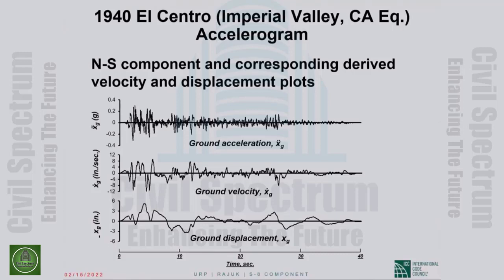I think I mentioned previously that earthquake ground motion is recorded by strong motion accelerographs. That is what the instruments are called, G-R-A-P-H. The instrument is a strong motion accelerograph, and the records that the accelerograph makes are strong motion accelerograms. The instruments are called strong motion accelerographs because they are triggered only when ground accelerations go beyond a certain threshold, so that every little bitty earthquake is not recorded. Those are strong motion earthquakes, generating strong enough ground motion that are recorded.